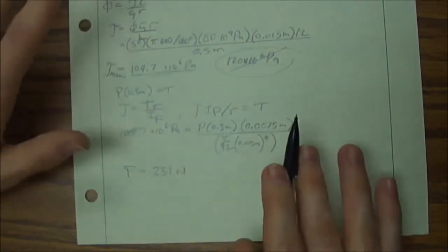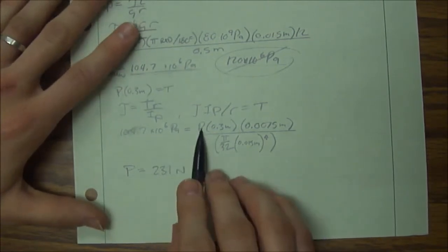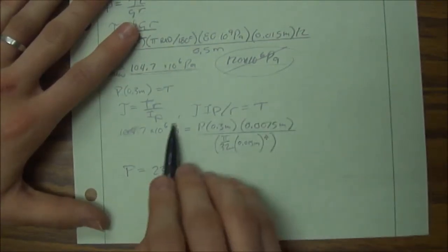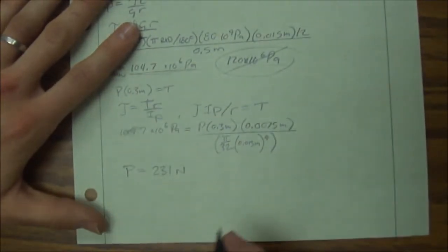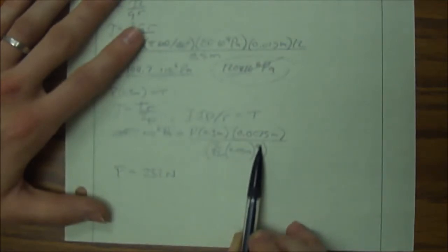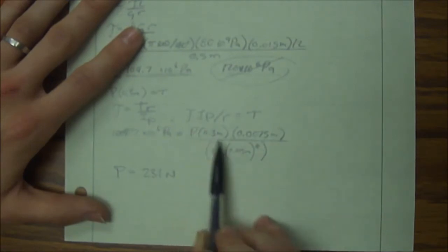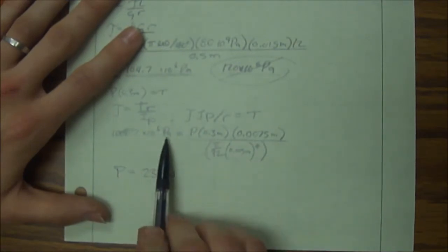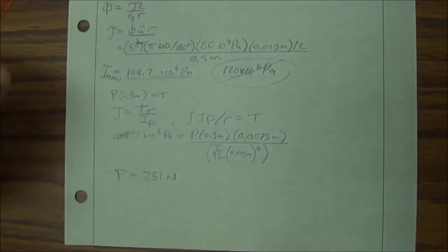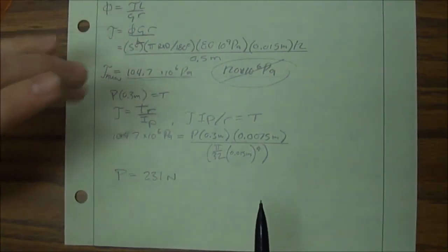Alright, I can still do a little unit check here. If this is newtons, if I plug this in, I should get pascals. So even if you mess up a little bit like I did, you could still check your units and find a possible mistake. So if I plug in newtons here, this is newton times meter, and I'm dividing by meters to the 4th. So that means that this is meters squared over meter to the 4th. It is newtons over meters squared, which is the definition of a pascal, which means my units are good. And we are done with that problem.